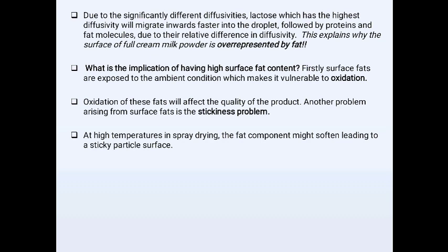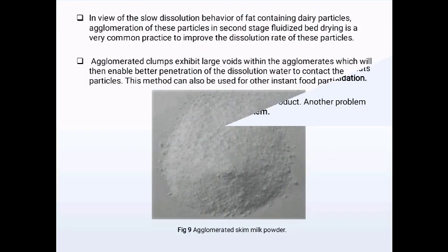Firstly, surface fat is exposed to the ambient condition, which makes it vulnerable to oxidation. Oxidation of these fats will affect the quality of the product. Another problem arising from surface fats is the stickiness problem. At higher temperature in spray drying, the fat component might soften, leading to a sticky particle surface.